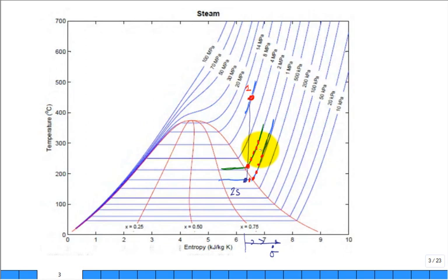Okay. So we recall our basic equation for what is the isentropic efficiency of a turbine. I like to break it into simple steps. So we have the work that you could get out of the turbine per unit mass going through the turbine. And if it's isentropic, that's going to be a larger amount of work per unit mass than the actual work out. Does that equation make sense? You go back to Thermo 1. Yeah, it's going to be 90%, 85%, something like that.